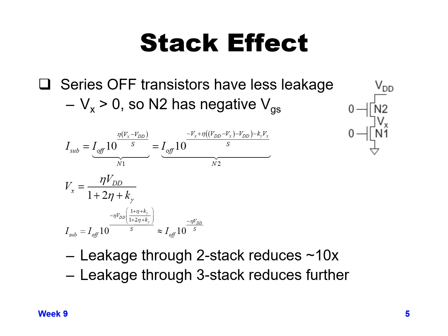If we turn both of those transistors off, since we have two devices in series, we'll have less leakage than you might predict. Normally, you might say maybe the leakage goes down by a factor of 2 because you have two series devices, so it's twice the length. But in effect, it goes down by quite a bit.